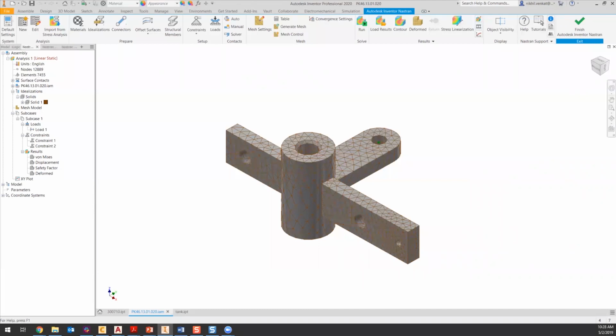Okay, so I believe you have a couple of questions here. Let's take a look. Yeah, so does that include a report file? No, it does not. If you generate the report separately, that's a separate HTML file that's going to be created. But again, you can put that in the Vault, and the thing is, you will have to keep re-updating the report file. It doesn't generate the report and put it in that same folder. In this case, if you were using item-based life cycles, I would just create that as an attachment and put it on the item itself.